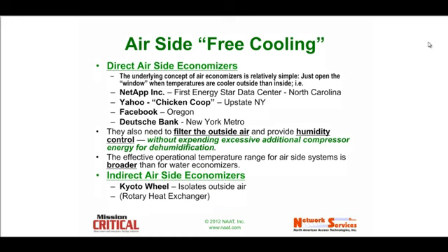And we have to get accustomed to the fact that newer equipment today is pretty rugged when it comes to that. If you're looking at legacy data centers with legacy equipment, you have to go back towards the recommended ranges. If you're talking about new equipment as the prime occupiers of the white space, then it allows us to explore more and more broader temperature ranges for free cooling.